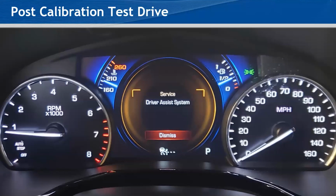We've changed the complete attitude and drive of the vehicle. So maybe just the windshield's been replaced, and that alone would warrant the calibration, of course. But if thrust angle plays such a big part in it, why would we not check it? If we're going to calibrate it, what if we calibrate it wrong after the windshield and the thrust angle's off? What if all of those factors would say that, yeah, we should probably check everything anytime we're going to do a calibration. Anything that could affect the calibration needs to be correct, even if we didn't touch it.